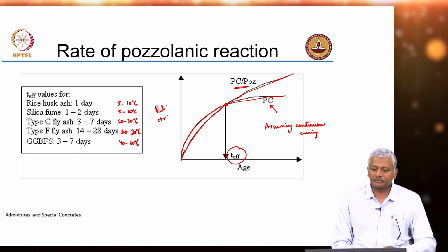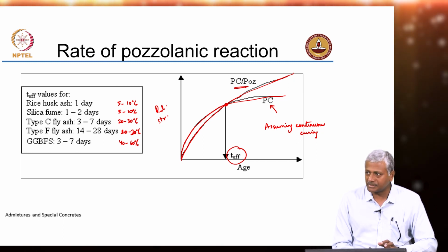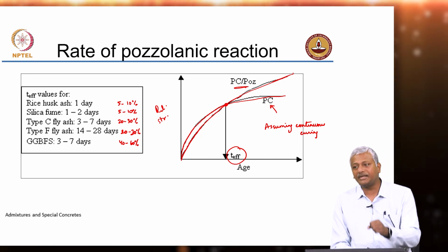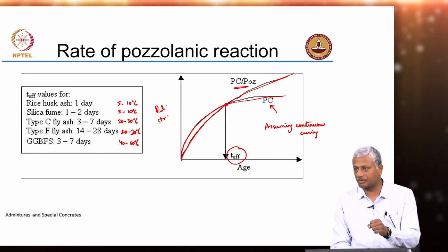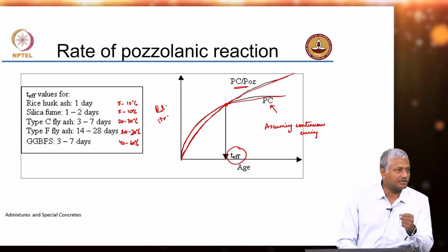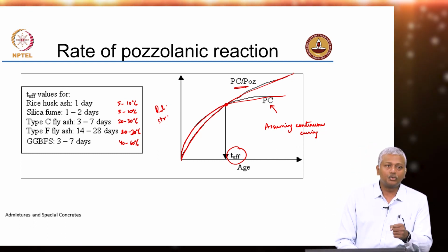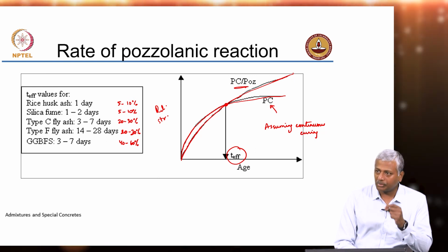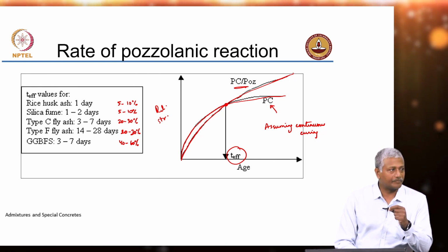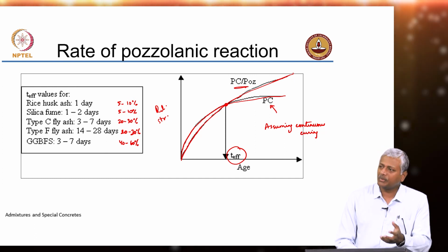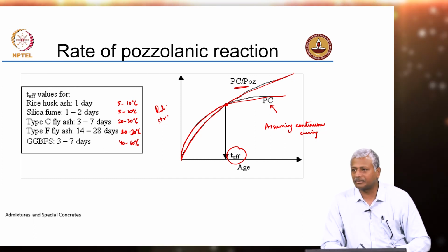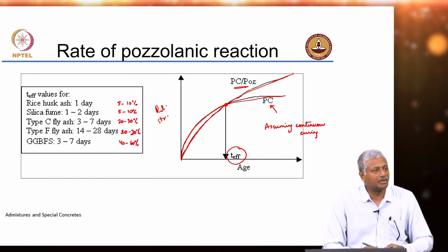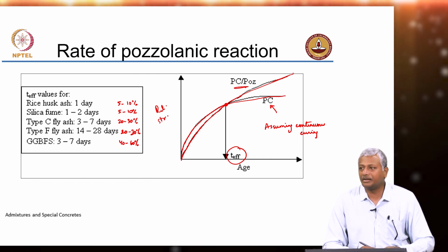So, this is a very important concept because it tells you that for an early age strength, when you are designing concrete, let us say 28 days strength, you will be limited by the extent of mineral additive that you can actually put in your system, right. Why do we talk about 28 day strength? What is the reason? Why do we want this 28 day strength? What is so significant about 28 days?